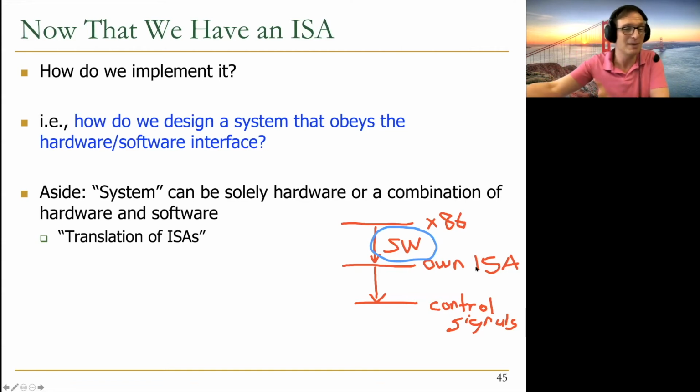So what we're going to implement is going to apply very much to these complicated ISAs as well, because internally, these modern microprocessors translate the x86 ISA to something like MIPS. And then they implement a MIPS-like ISA in the microarchitecture. So basically, this changes the trade-offs that you make. You can take a completely different ISA and execute it on your hardware very efficiently if you can do this translation very efficiently, in software or hardware.